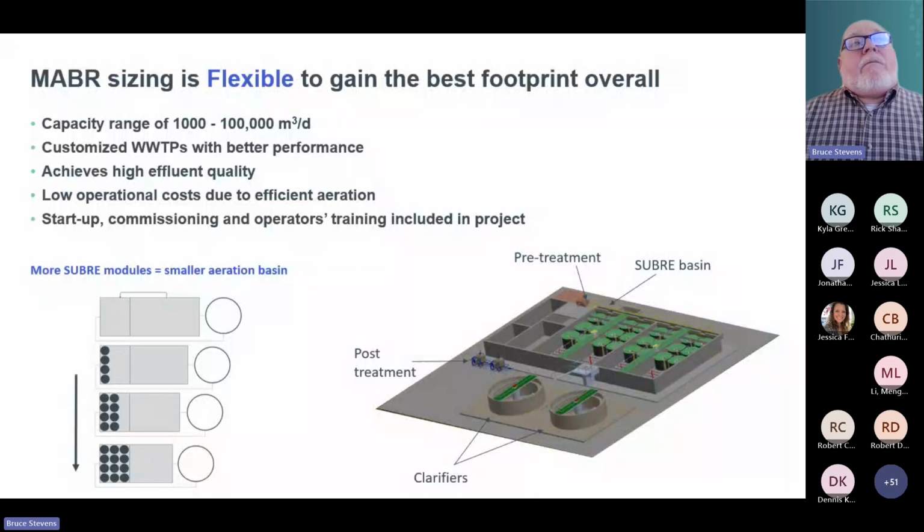And the flow that comes through is then clean of all that trash that would otherwise get stuck in the MABR towers. We don't want that in there. Just like an MBR, a regular membrane bioreactor plant with cassettes, you don't want all that kind of trash. Everybody uses fine screens in those as well for this purpose. And we really want to avoid getting the fats, oils, and greases in there because it will foul the membrane surface, and we don't want that there.